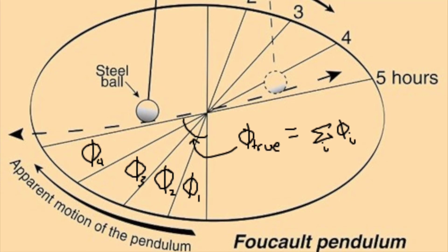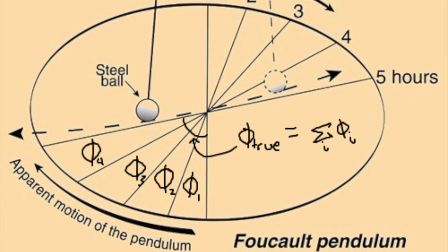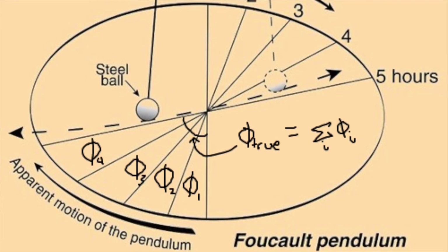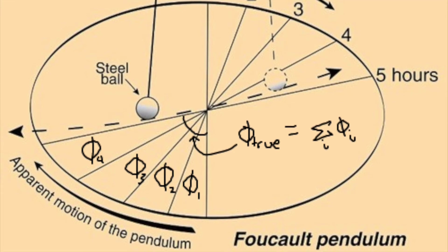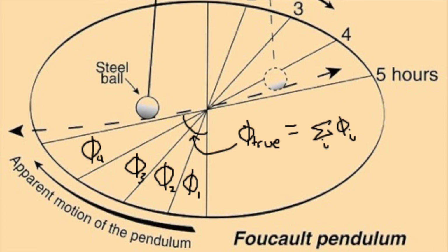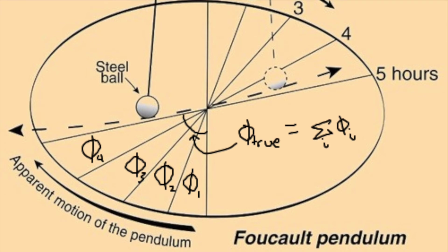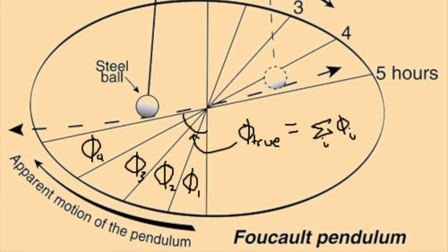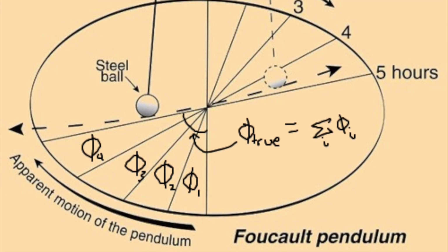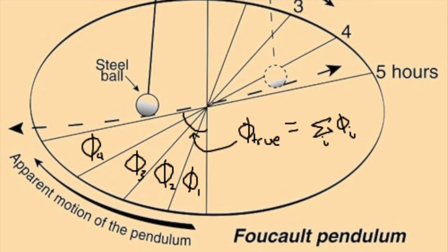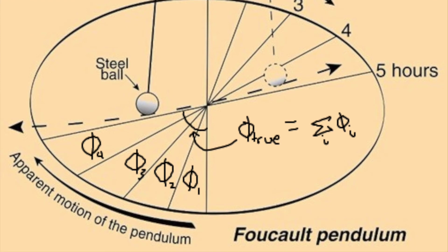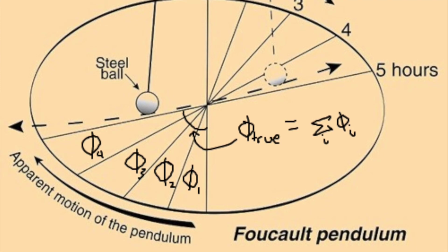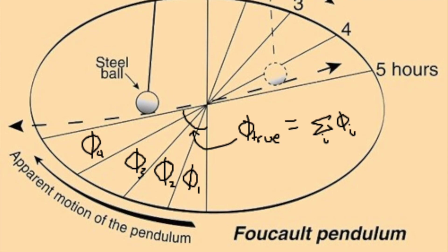Every time we calculate a value of phi, we compare the value with the last calculated value of phi to determine the change in the angle since the last recording. This is added into a separate angle variable, which we will refer to as true phi. The reason for this is so that we may record the angle at which the pendulum has rotated since the simulation began, rather than simply measuring the angle it's at now. This allows us to tell if the mass swing has rotated 2 pi radians, 4 pi radians, or more, rather than just being limited to the negative pi to pi range.